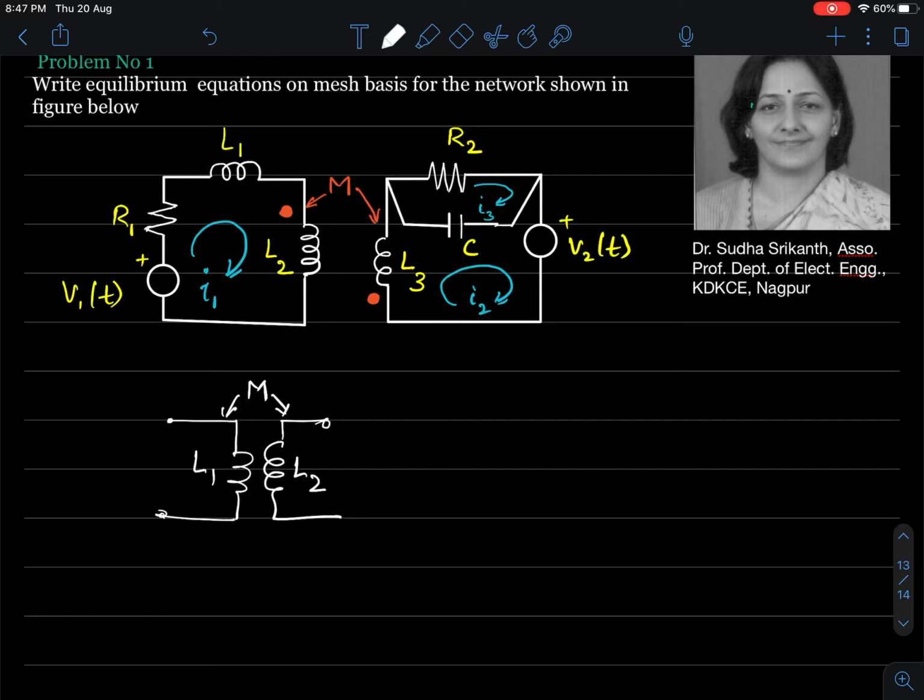So we need to know the direction of winding of the coil on the limbs of a core, if it is an iron cored inductor. If you imagine an iron core inductor, could be a transformer for that matter, with two coils wound on the limbs, it depends on the direction of winding. The flow of current in these windings is capable of producing either aiding fluxes or opposing fluxes. So not always is it possible for us to look at the winding. So in order to simplify things,